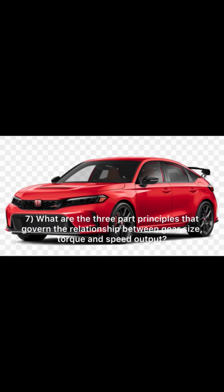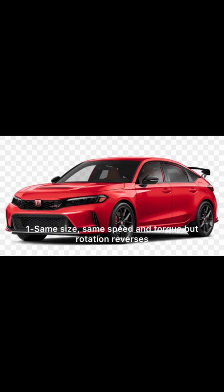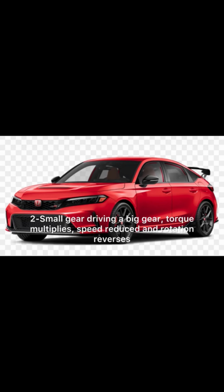7. What are the three-part principles that govern the relationship between gear size, torque and speed output? 1. Same size, same speed and torque, but rotation reverses. 2. Small gear driving a big gear: torque multiplies, speed reduced and rotation reverses. 3. Big gear driving a small gear: reduced torque, speed increase and rotation reverses.